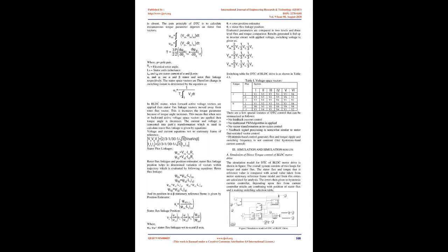2. Block diagram of topology. The block diagram for DTC control of BLDC motor drive is shown in figure 1. From the BLDC motor, flux and torque reference is taken, which is compared with the estimated value of torque and flux. Depending upon this, the hysteresis controller applies the parameters for voltage space vectors that are applied to the BLDC motor with the help of the inverter.